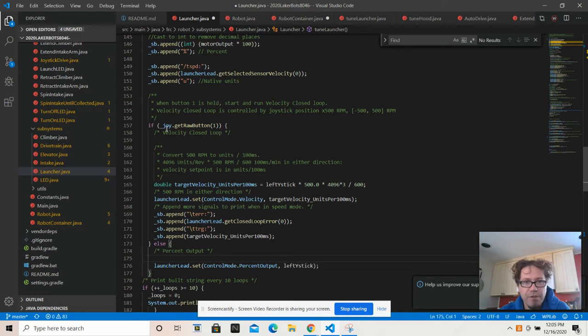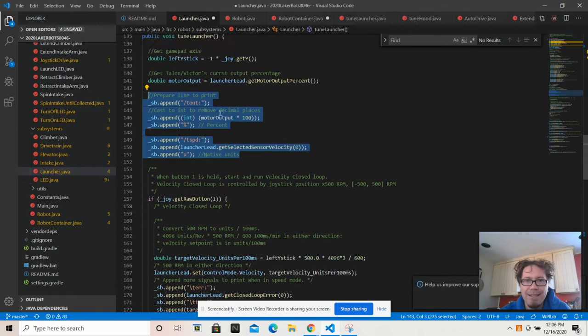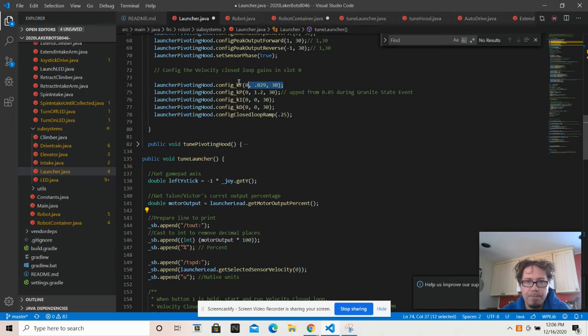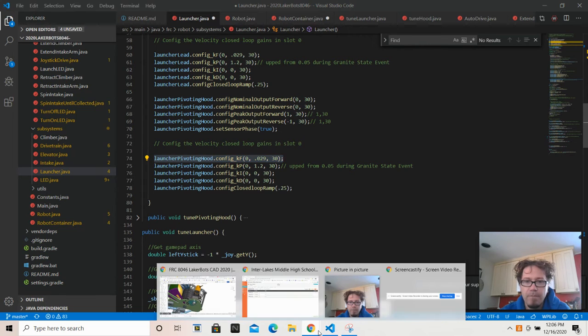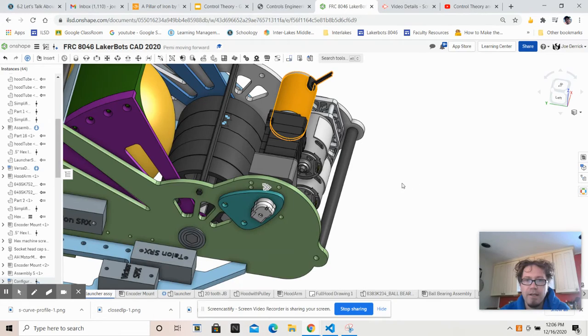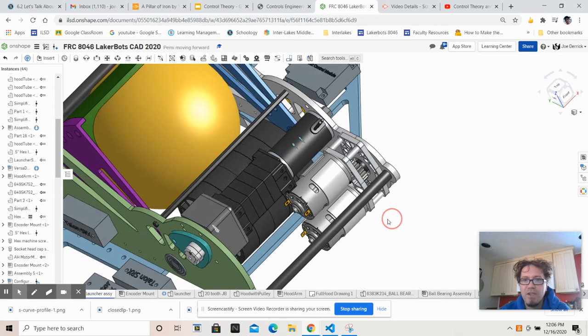So what we'll do is not push the button at first, ramp it up to full throttle so that we can measure the output. And based on that output that's given, we can then assign an F value. Right here, what we did was we just took the F value from the launcher motor and copied it as a placeholder. But if we think about the F value as what's called the feed forward, and basically relating the motor voltage to encoder velocity, because we have